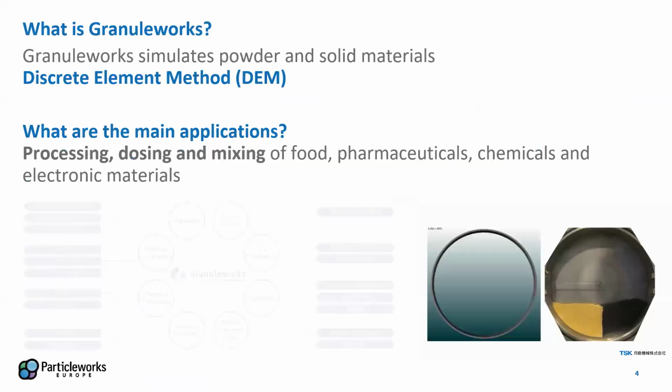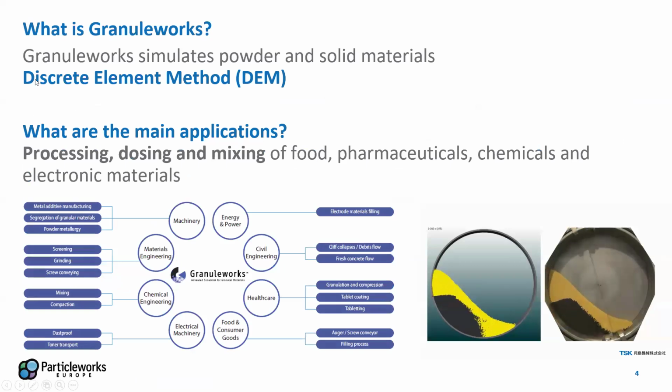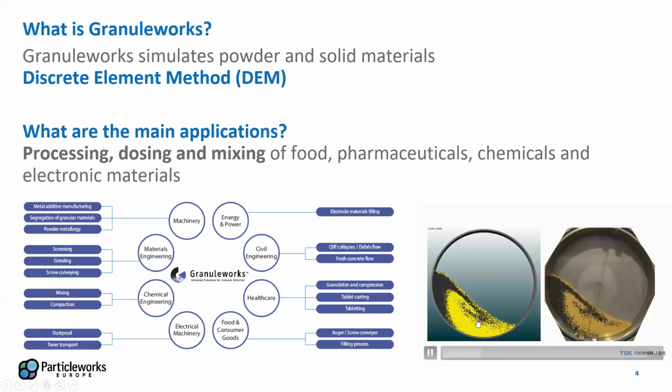Granuleworks is a meshless tool for powder simulation. So it means at the beginning of the simulation, each granular element is discretized automatically by the software, and we don't have to have a computational mesh generated in advance.